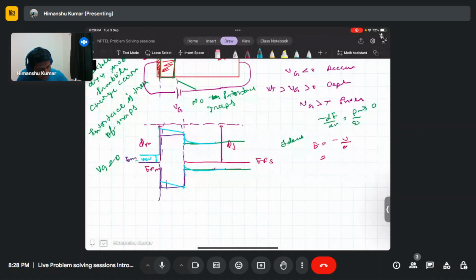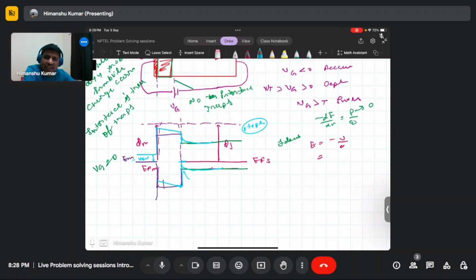So similarly, you will see here, as you can see, if you draw this, this is a p type substrate, and you can see that at the interface the Ef and the conduction band are coming much closer. So the interface is becoming more p type, and since this is a p type substrate, a large number of holes are available.